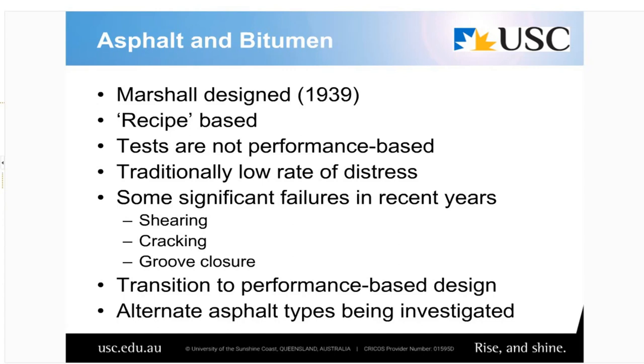Anybody who's seen me talk about asphalt at some of the conference events would have heard reference to Mr. Marshall, who developed our method of designing our asphalt mixtures in 1939. It was a bit adapted by the US Army Corps of Engineers shortly thereafter, but it essentially hasn't changed since 1950. Mr. Marshall's method is very recipe-based.